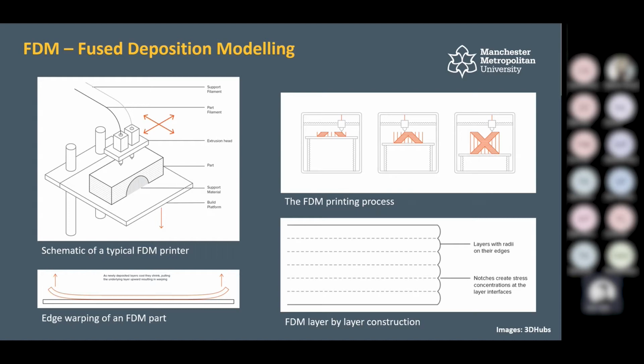Again, there are ways around this. Changing the material, for instance, is a common one. If you change it to ABS, or if you use various additives on the printer, that can help resolve these issues. Splitting the model up and printing it as a smaller volume at a time will help. Making sure the build plate is a heated build plate keeps these temperatures nice and warm, which keeps it flat. So again, things to consider.